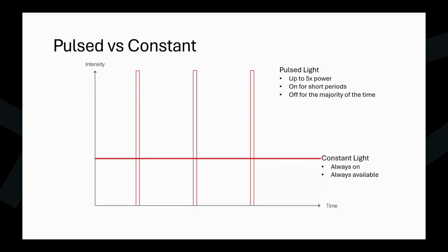And this is actually quite an interesting thing, because some customers will look at these products side by side and consider them to be the same, or I even got asked a few weeks ago how it really works, because they thought that the pulse products were simply just the same product turning off and on through the camera shutter speed. But actually, if you broke those open, they're entirely different products, and there's electronics in there that allow us to drive the power considerably higher, but obviously using the same sort of like heatsink real estate, etc. Because it's only on for such a brief amount of time, you're not going to overheat the LEDs, and you're going to keep the overall lifespan of the product exactly the same.